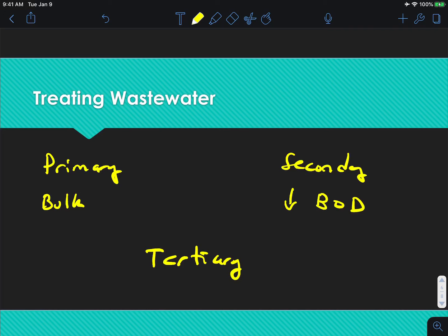A lot of what we do for drinking water is specialized steps. It's very similar to what's done for tertiary only, a group of tertiary things. You might think of it like that. We don't call it that because it's not wastewater treatment. But if you're familiar with things like reverse osmosis, carbon adsorption, if you have a water pitcher at home, like a Brita or a Pur, that has a little filter you put in it, that's filled with a carbon material that has a great adsorption capacity, and it'll remove lots of things like organics and heavy metals. Reverse osmosis is just pushing water through a membrane to filter things out. So there are all different types of things you can do to treat your drinking water.